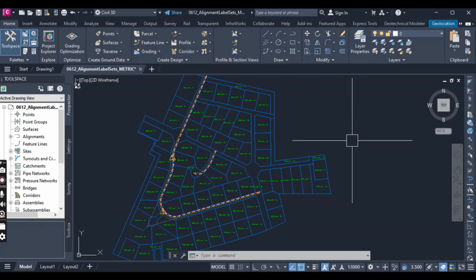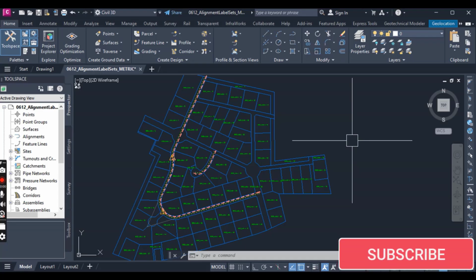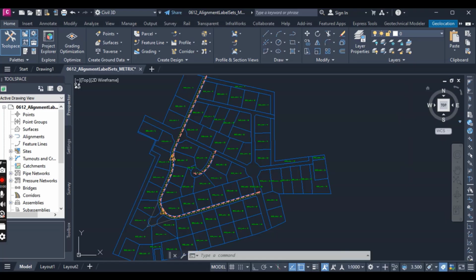Hi students, labeling in Civil 3D is one of the program's strengths, but it's also an easy place to get lost. There are many options for different labeling situations. Spread can be difficult. When you think about it, any number of items can be labeled on an alignment. These include major and minor station geometry points, design speeds, and profile information. Each of these objects will have its own style.